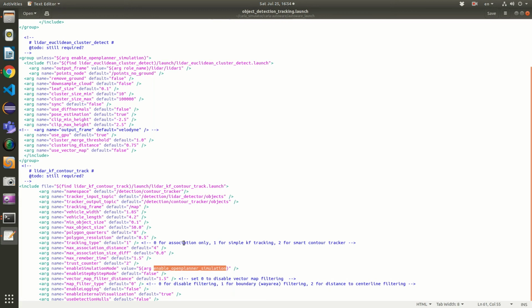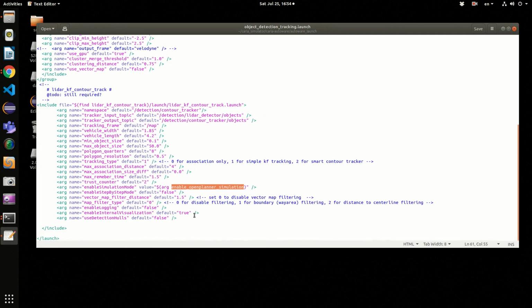This will actually be so handy if you are testing with a real vehicle. So we can run the vehicle as if it sees some obstacle, but the obstacle is not there. Then we can test the behavior of the vehicle for an existing obstacle, or obstacle shape, or another leading vehicle which is not there. It's safer to do that, and I will show in the next tutorial how to do this kind of virtual simulation. And we can call it hardware in the loop, or the actual vehicle in the loop of testing.